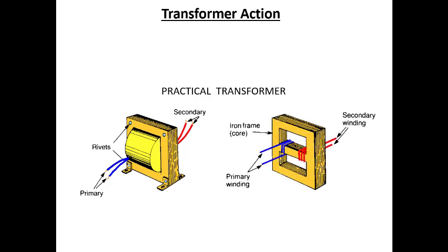And what we would be seeing is that this big thing here is the loops of wire. And so a lot of transformers are made in this kind of figure 8 configuration for the core. So this is the core of the transformer. Usually they'll make that using iron with laminations. And then there's a primary winding, and then there's a secondary winding.